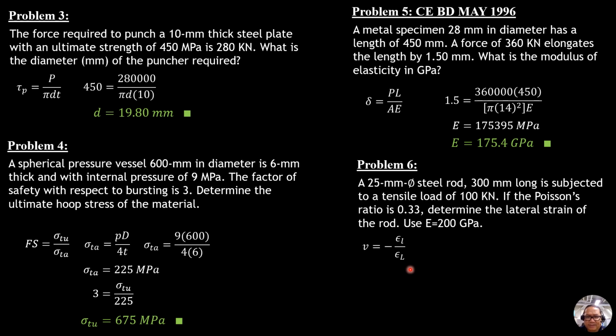We can compute the longitudinal strain because it is just force over area, or PL over AE.